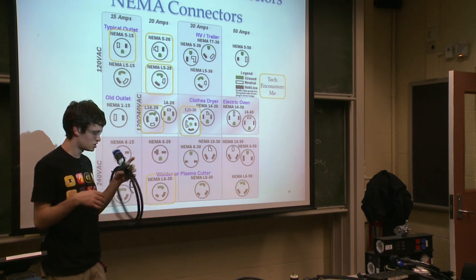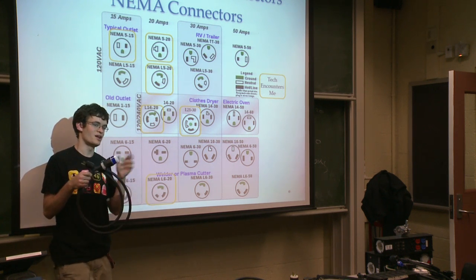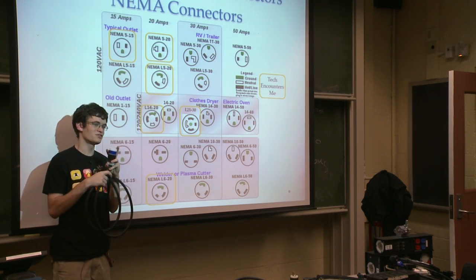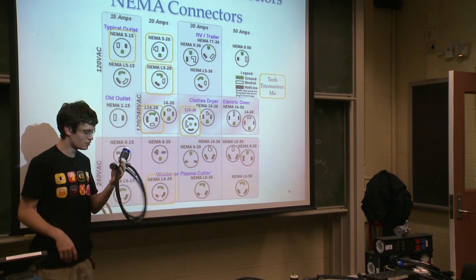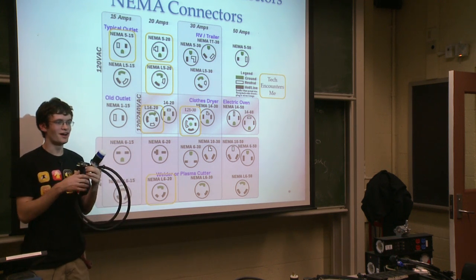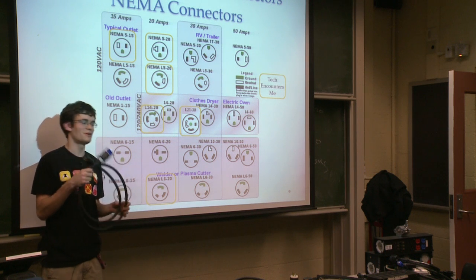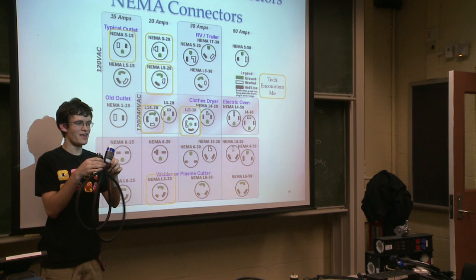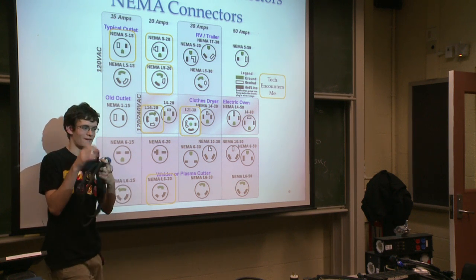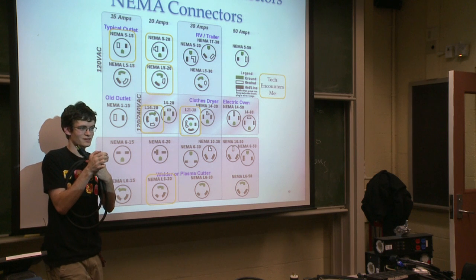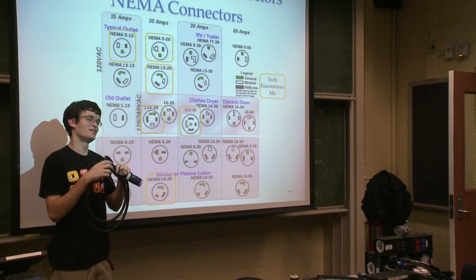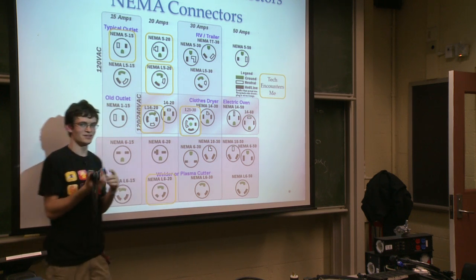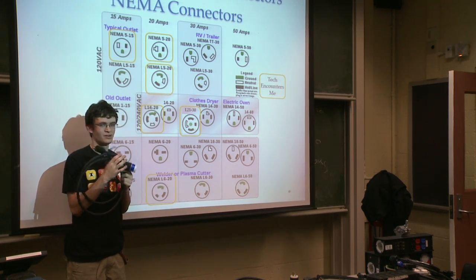At one point, there was a show where we had lights that had L6 connectors on them and they were molded connectors and we didn't want to replace the connectors or take them off. So we made Evil Demon Christmas cheaters. They were called Christmas cheaters because they had green and red tape on them that were the reverse of this. And they were bad. They had a female of this and a male of this for instruments that could take 120 to 208 but had the wrong connector on them, and we only had 120 circuits available or 208 circuits available. And that is horrifying.